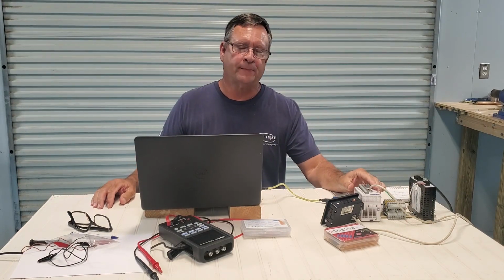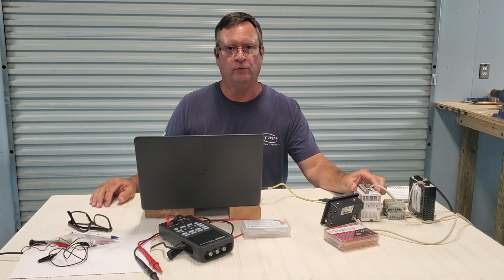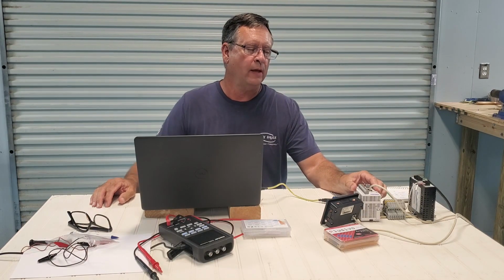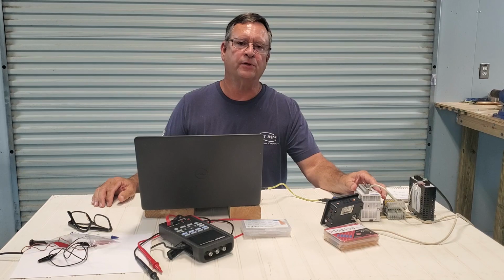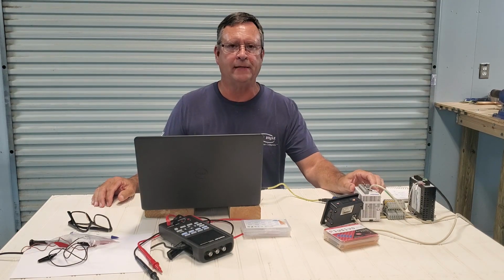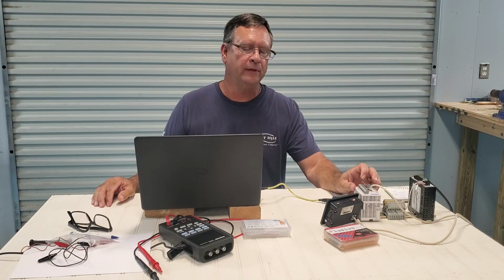This one is a temperature measurement without the control, just a temperature measurement. There's still plenty of room in this PLC unit for the control. For this, I'm measuring temperature without a temperature module. All I'm adding into the PLC itself is one 10K ohm resistor and one thermistor.